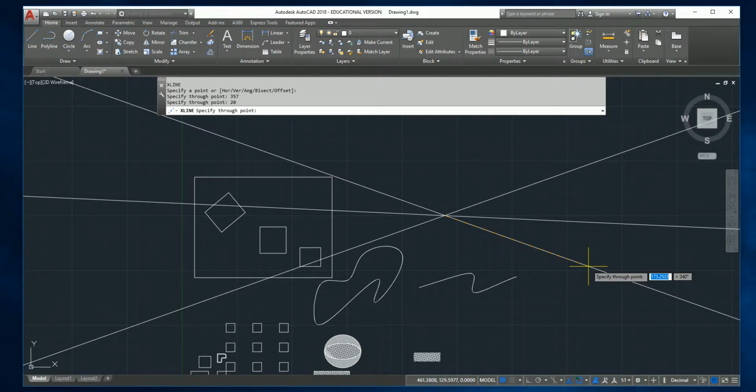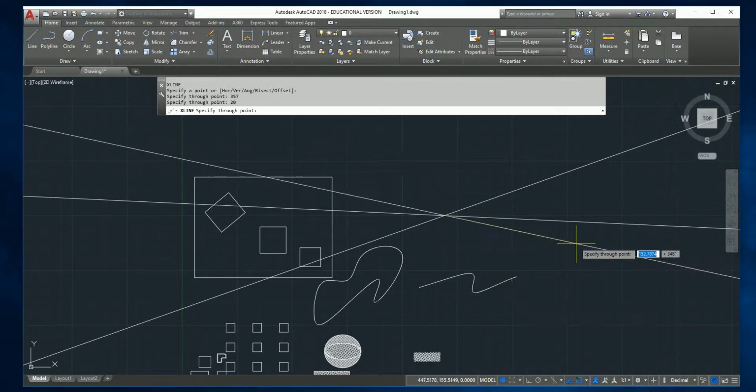Especially, in the drawing world, everything's perfect 90 degrees. In the built world, nothing is. But we want to draw it in 90 degrees because there's tolerances and different things like that. Like the old saying, get as close as you can and cock it, right? But it's just a lot easier when you're drawing, especially when you're starting out, to draw stuff in ortho. It's going to help a lot. Make sure you're stretching in ortho, you're copying. Maybe when you're rotating, you turn the ortho off because you may want to rotate it at 45 degrees, 30 degrees.